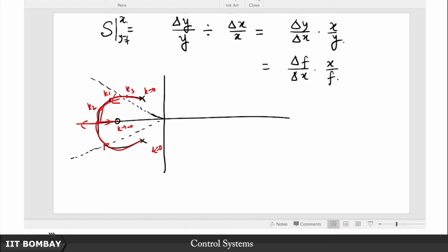So this line is telling me that my roots better be within this sector in order to meet the damping criteria. What is the damping criteria? It is basically nothing but another way of translating the percentage overshoot. If you recall our discussions earlier, you would know that damping ratio is clearly related to the percentage overshoot alone, right. So now clearly if I have increased my k3 sufficiently, I will meet this condition, but the question is how much should I increase k3, yeah.